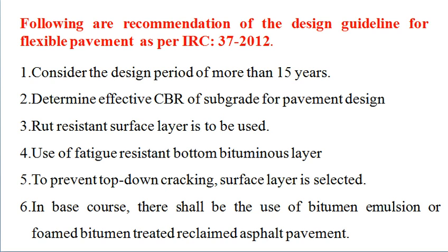Next was the use of the fatigue resistant bottom bituminous layer. So, the introduction of bitumen in the below lying layers. Now that might be the base course, the sub-base course. These layers were introduced with bitumen. So this introduction of bitumen into these below lying layers, apart from the surface layer, actually enhanced the fatigue resistivity of these layers.